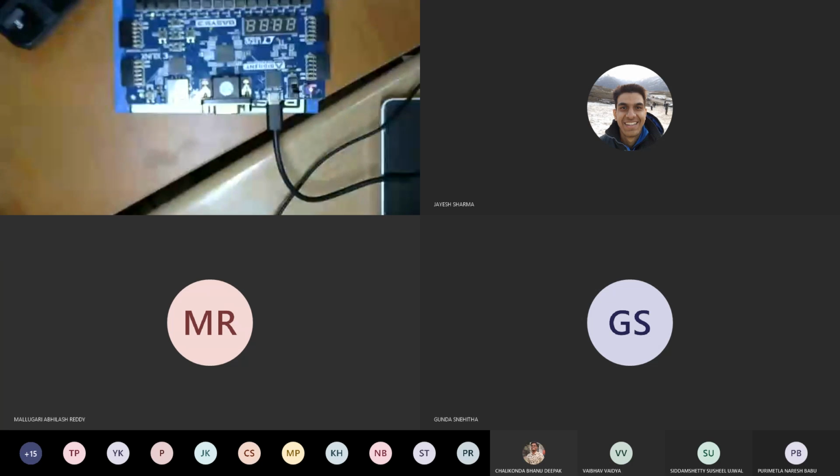Okay, so now as I said, it was in the background, so I just close this project. As I said, I already have this JK flip flop project. I'll quickly show: open recent. Again, you follow the synthesis, implementation, and bitstream steps, and then I'm just programming it. So open target, auto connect. Then it should be able to find my board.